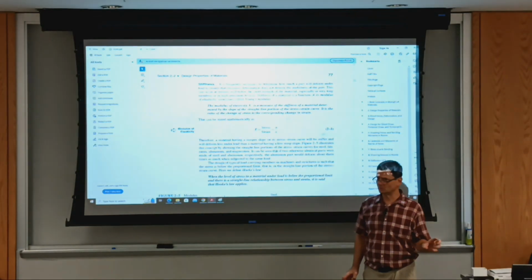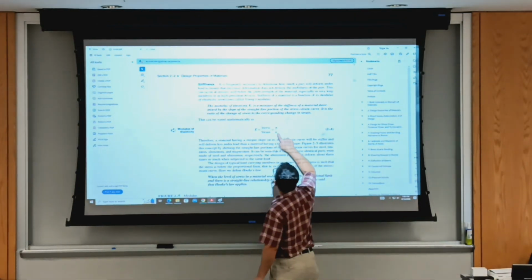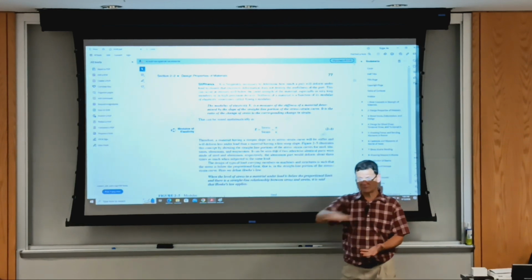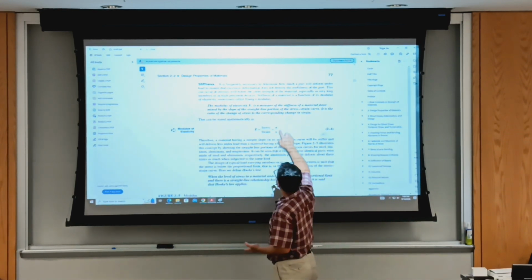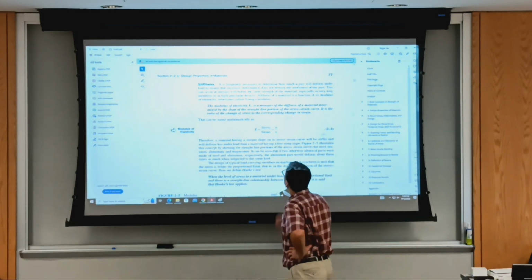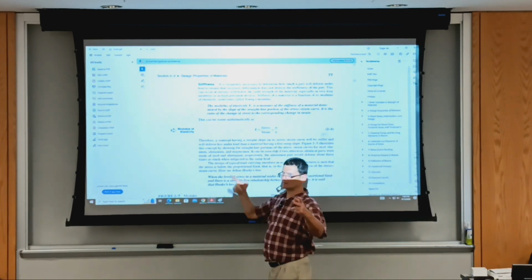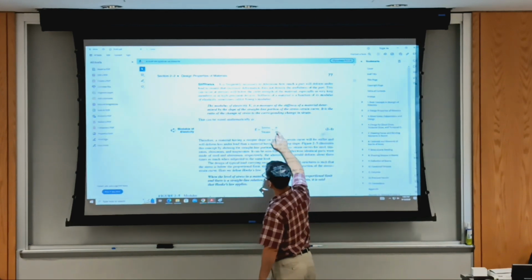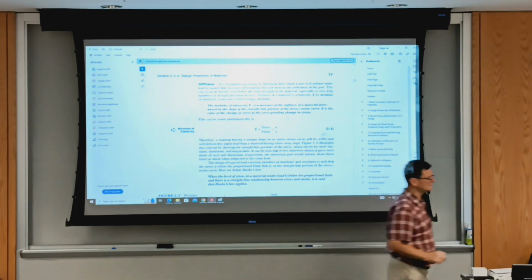Have you heard of modulus of elasticity? Okay, great. So this is sigma, the stress: load applied to the specimen divided by initial area. You don't update that area again. Sometimes, to be correct, you call it engineering stress. And then strain: final length, or current length, minus initial length, divided by initial length. It's unitless strain.